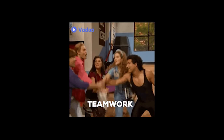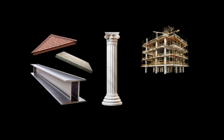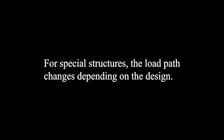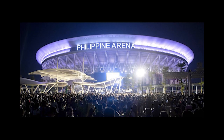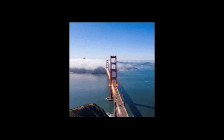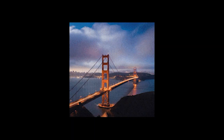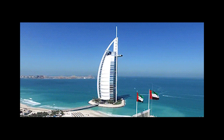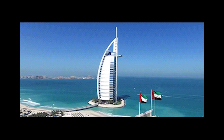To summarize, load path is the route that forces follow through a structure until they reach the ground. For common buildings, loads usually travel from roof or slab, then to beam or truss, then to column, foundation, then down to the soil. For special structures, the load path changes depending on the design. The Philippine Arena uses a large span steel space frame. Suspension bridges use cables in tension and towers in compression. The Burj Al Arab uses a concrete core, steel exoskeleton, and deep foundations.